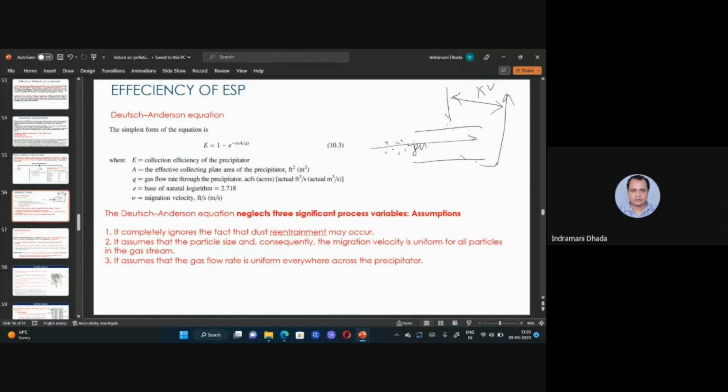These ions will stick to the particles, and the particles acquire charges, some positive particles and some negative charge particles. There are certain electrodes, these metallic plates, and the positive particles are attracted towards the negative plates, and the negative charge particles are attracted towards the positive plates, and the clean gas will be removed. In terms of particle removal technology, ESP is very good.